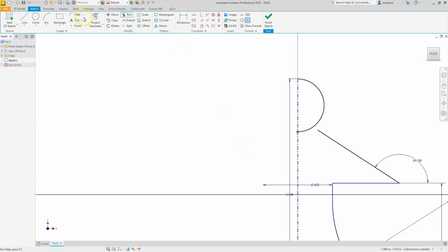Let's go ahead and put a dimension on this one. I'm just going to use the dimension, select here. Now this one has a diameter dimension of 0.75. So I can either do the math, or I'll have to escape out of this and do this one again. I just noticed it was a diameter dimension. So you can either do the math and type in half of 0.75 in our case, which is 0.375, or we can have Inventor do it. I'll show you both ways actually.